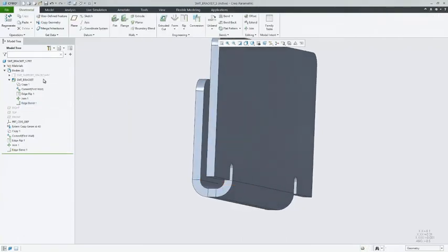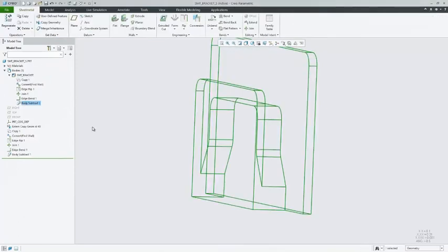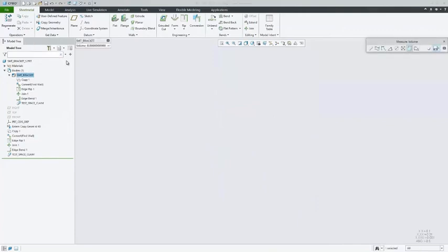As a quick intermediate test whether the sheet metal geometry still respects the maximum space claim defined by the original construction body, we can use Boolean operations to subtract the construction body from the sheet metal bracket body. For the test to be successful, this operation needs to entirely consume the geometry and the remaining volume of the sheet metal body should be 0.